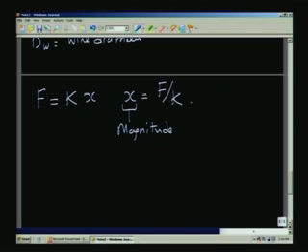So, if you want to have a reasonably small value for the displacement, one would like to go for a large spring constant, or another way to put it is the following: if we want to measure large forces, we of course will require a large spring constant. That means that the same spring balance I cannot use with infinite range. I cannot use it for measuring a very small force or a very small weight. I cannot also use it for measuring a very large weight.